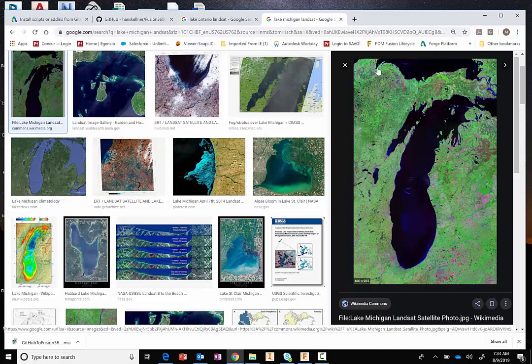Then you might want to use a tool like GIMP or Photoshop to clean the image up. I tried turning it to grayscale. It didn't seem to matter having it grayscale or not. But what does matter is the size of the image. I typically try to keep the image under 2,000 pixels just from a speed and performance perspective. And scaling the image has no effect on the accuracy or the contour shapes that it generates.